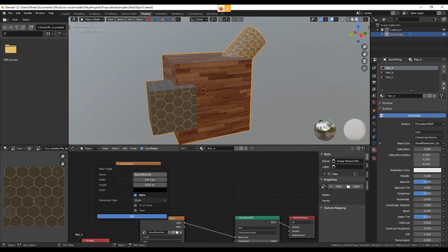And the size of this matters. If we want a decent resolution, I'm probably going to go with double what I have now. This says 1024. I actually want 2048, which is 2 times that. Here's a little trick for you Blender people. If you leave the original dimension there, 1024, and type asterisk for times 2 and hit enter, it'll double it for you. So it can figure out the math. We don't need any alpha channel, and it'll just be blank. And we'll hit OK.